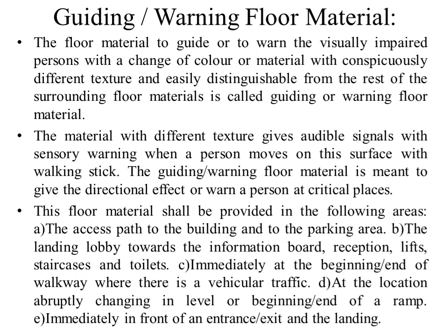This floor material shall be provided in the following areas: the access path to the building and to the parking area; second, the landing lobby towards the information board, reception, lifts, staircases and toilets; and immediately at the beginning or end of the walkways where there is vehicular traffic, and at locations abruptly changing in level, or beginning and end of the ramp, and immediately in front of an entrance, exit, and the landing.